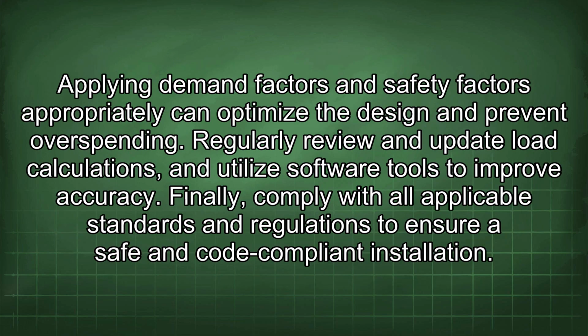Applying demand factors and safety factors appropriately can optimize the design and prevent overspending. Regularly review and update load calculations, and utilize software tools to improve accuracy. Finally, comply with all applicable standards and regulations to ensure a safe and code-compliant installation.